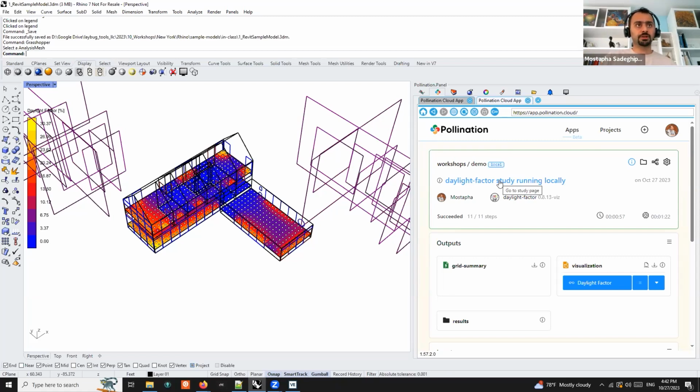Masume, do you have a question? Yes. I wanted to ask about daylight simulation purposes. In case I want to do some daylight simulation, do I need to model room by room, or is it fine if I just make the exterior skin as a big room, and then as interior walls, I put just some vertical surfaces as shading? Yes, you can totally do that.